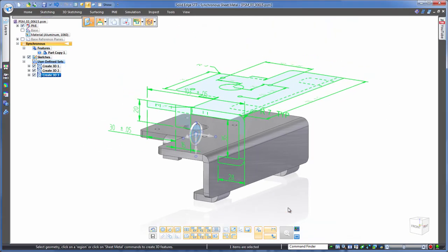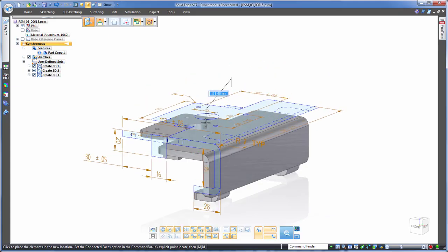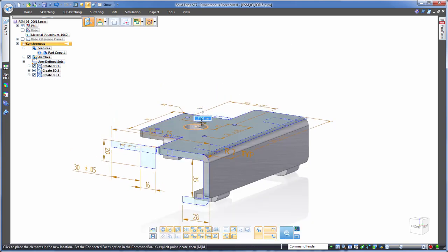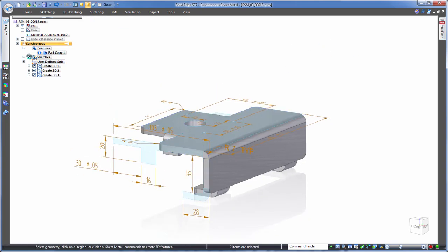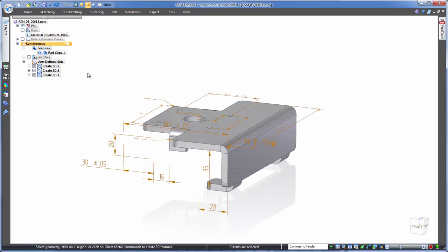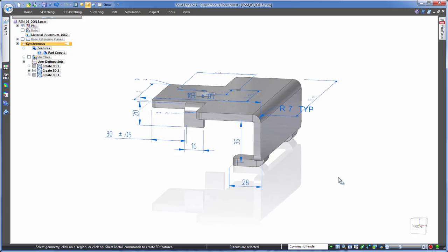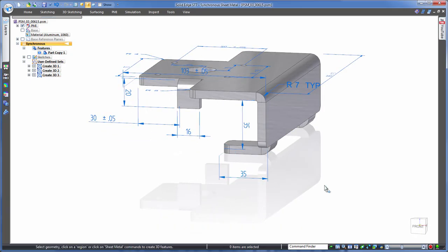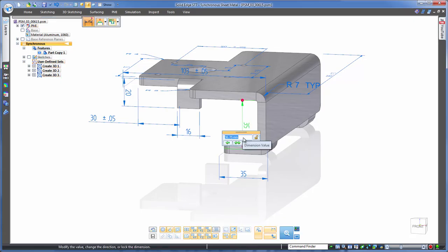Now you've already seen this steering wheel in action editing 3D geometry, and to keep things consistent, it can also be used for things like this, snapping drawing views into position over the model. So, nice to see the manufacturing intent overlaid in 3D, but wouldn't it be useful if we could control the model with these dimensions? Well, Synchronous Technology in Solid Edge can do just that. A simple click to attach, and these dimensions are now live, enabling us to make the required changes that we need whilst maintaining this manufacturing intent.